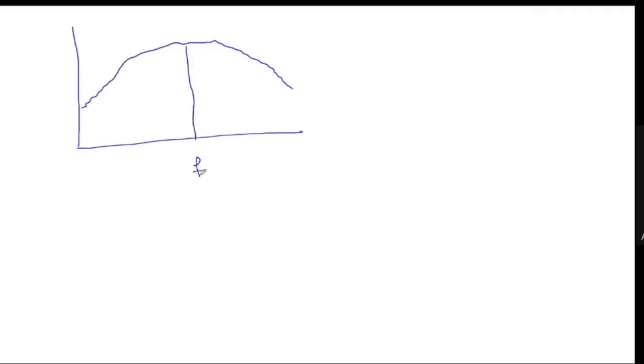For example, if this is the vertical axis and this is the horizontal axis, the combined spectra look something like this. There were vertical lines representing the undamped natural frequency of the system. And on this vertical axis was the velocity, normalized by the ground velocity of the input, and this was the velocity of the single degree of freedom system.